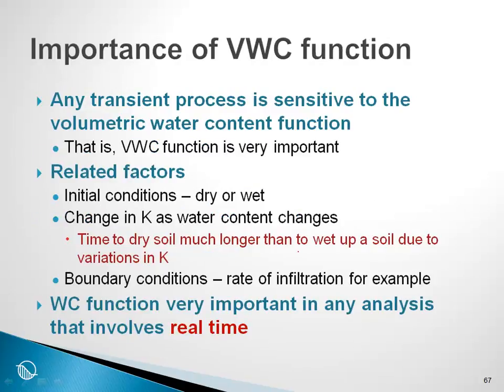The next question, what is the importance of the volumetric water content function? Any transient process is sensitive to the volumetric water content function. In other words, the volumetric water content function is extremely important to any transient process. Recall from our earlier discussions, it is the volumetric water content function that describes the soil's ability to store and release water, and it's the slope of the curve that's directly related to the rate of change of the water content, which is related to real time.